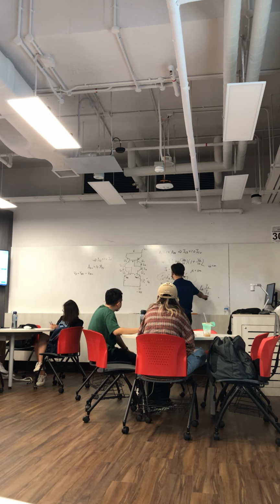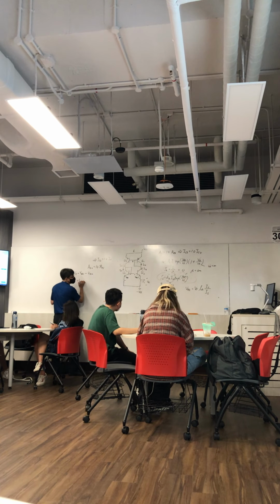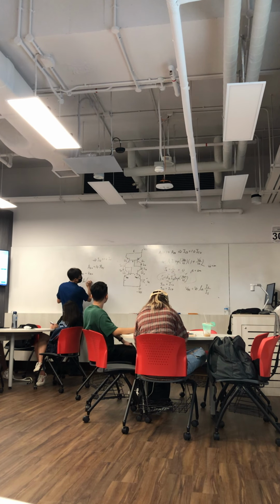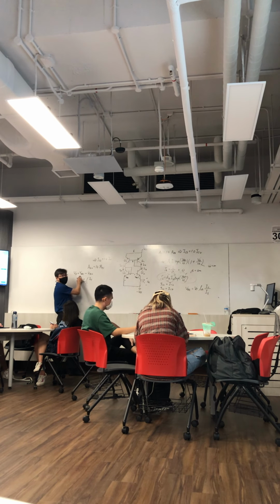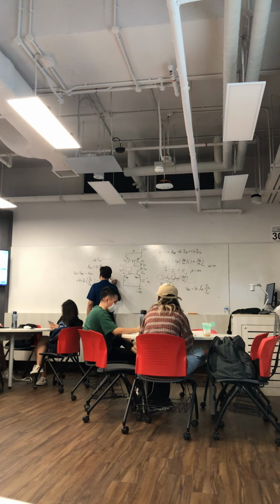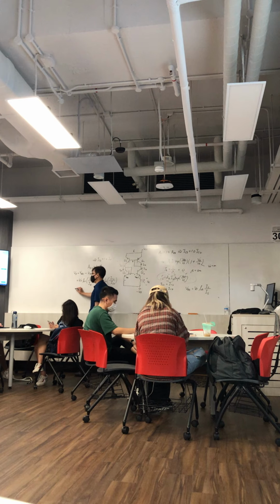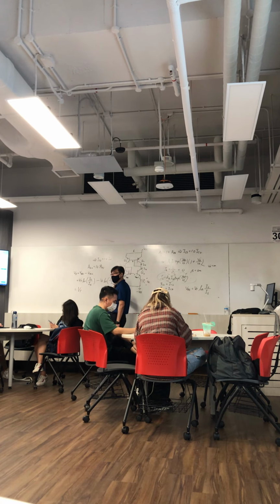Is it okay? So if it's okay, then can you express VBE1 in terms of the thermal voltage: VT log IC1 over IS1, minus VT log IC2 over IS2. If this is okay, can I pull out the VT, and then this minus this, right?